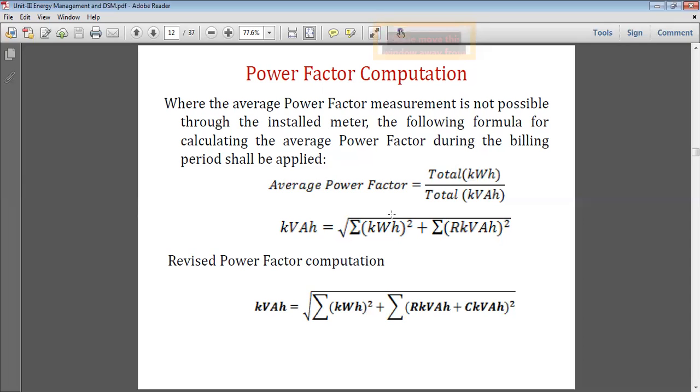So when there is automatic power factor control, as soon as your load decreases, the number of capacitors decreases. For example, in our college we have a 100 kVAR capacitor bank, divided into a number of steps: 20 kVAR plus 20 kVAR, this is the second step, then 15, 15, then 5, 10, 3, 2. In this way you can arrange the number of steps, and it will give a smooth variation in the power factor.